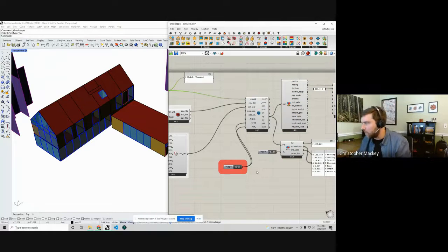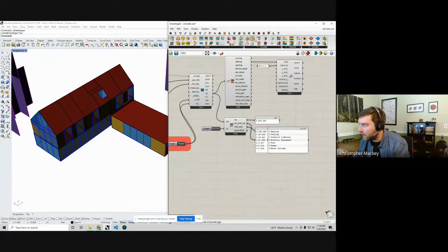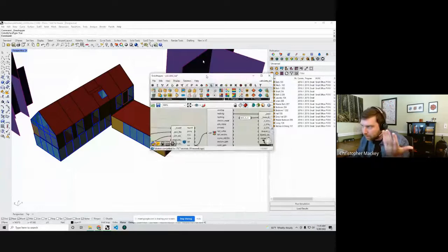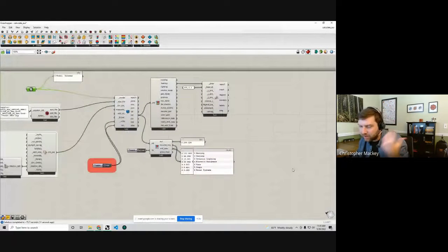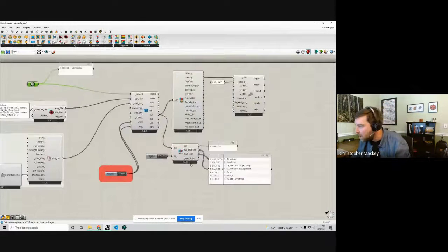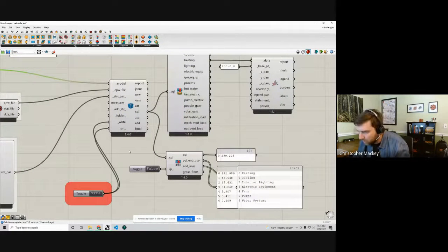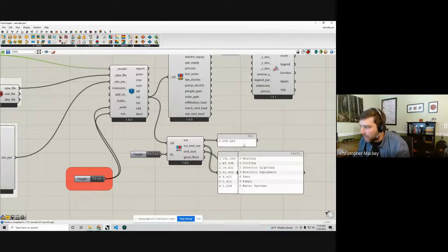So, all right, in this case, the simulation finished running, and you can actually check. I ran this with a baseline packaged VAV system, which some of you, if you know the building code, I know we had a few engineers here, know that this is about the code baseline system that you'd run for a small office like this. And you can see we get an EUI of about 300 kilowatt hours per square meter, which is about 95 kBTU per square foot, right?